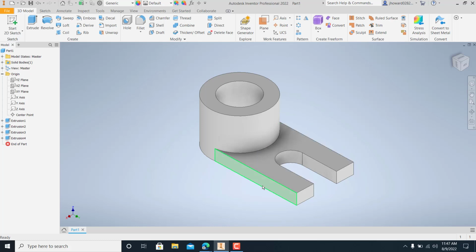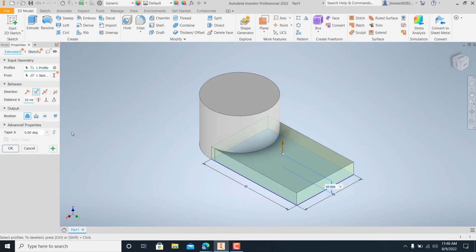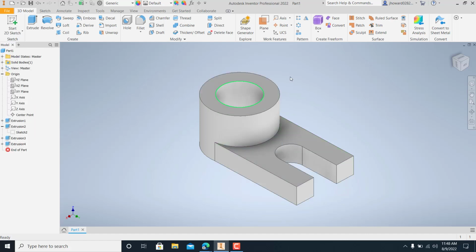And looking at it, I believe that this is too thin right here. All right. This is the beauty about parametric modeling. I can go back in and find this that I made. Remember that primitive solid piece? Right there it is. Do you see it? I can come in here, and if you want to fix the sketch, we're going to talk about that in our next unit coming up, but I can go to extrusion 2. Actually, there we go. Double click it, and I can change it. I can change it to 15 millimeter. Y'all see that?